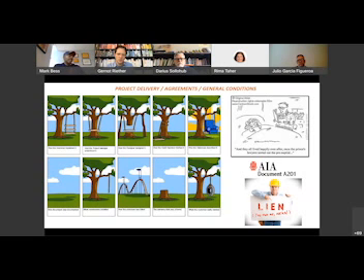Then we transition over to the AIA 201 general conditions, which the way I package it is almost like the handbook for construction. What do we do during the construction phase? Why is this document so important? We unpack the major focuses of it, such as bonds, insurances, and submittals. We look at payment applications. We understand what substantial completion is and how architects need to function during those roles, during those time frames.